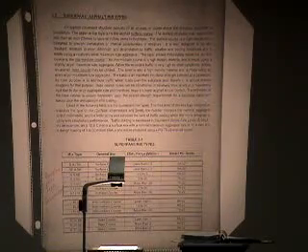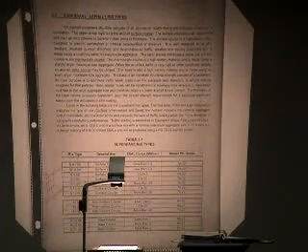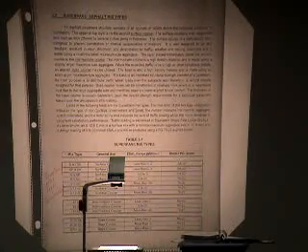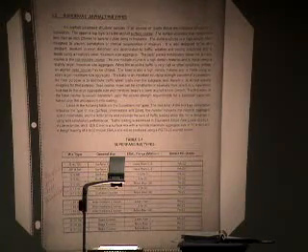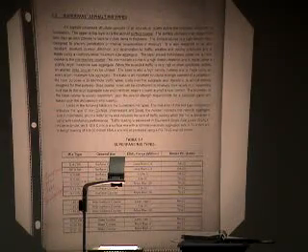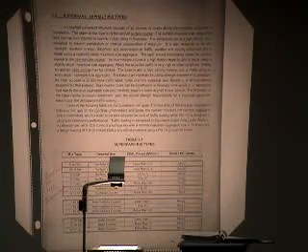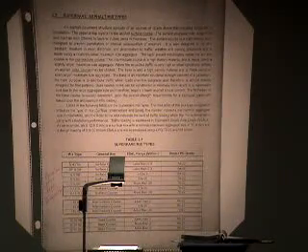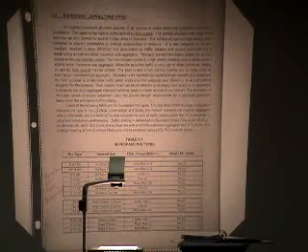Those binders are supposed to be selected for a given pavement based on the expected performance of that pavement under a given condition. Pavements with lower traffic can have not only less thickness, but you can use, I won't say inferior materials, but they don't have to be as high quality as you would want to use in pavements that have a lot of traffic. So that was the basic concept. You would come up with a pavement and mix that would perform based on the expected performance and the conditions under which it would be exposed.